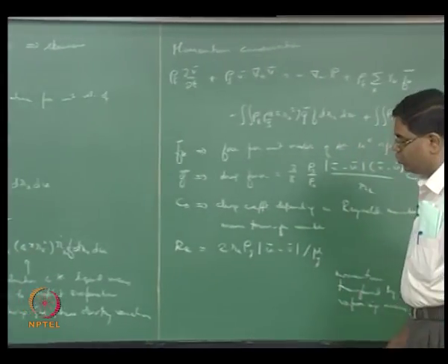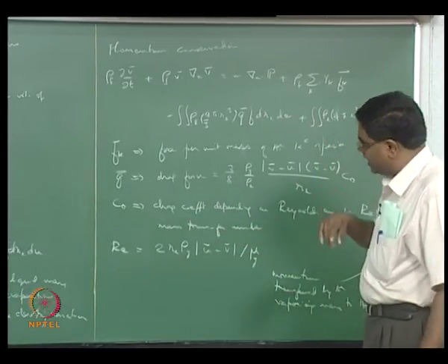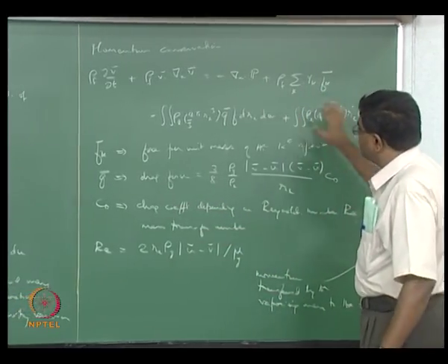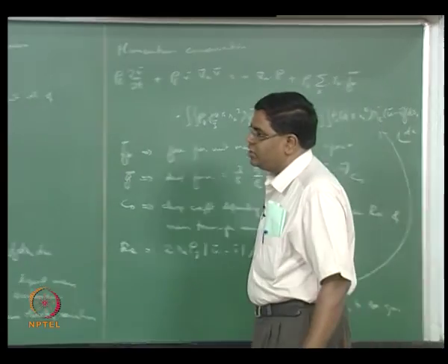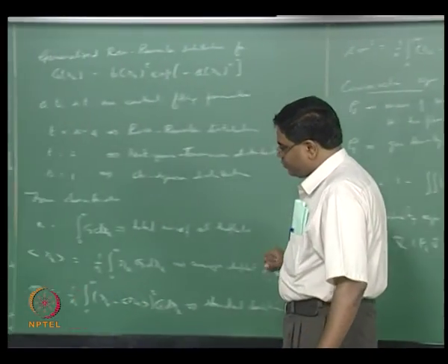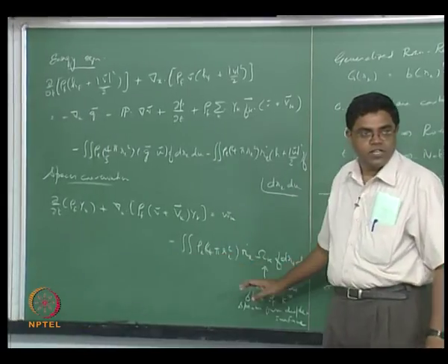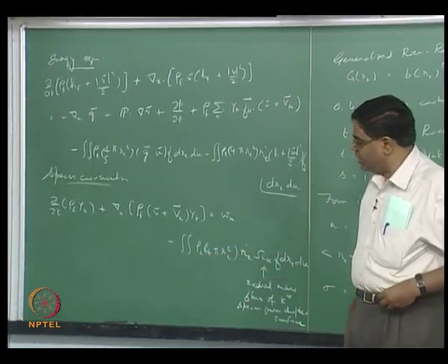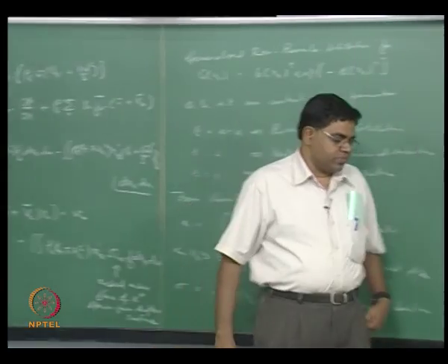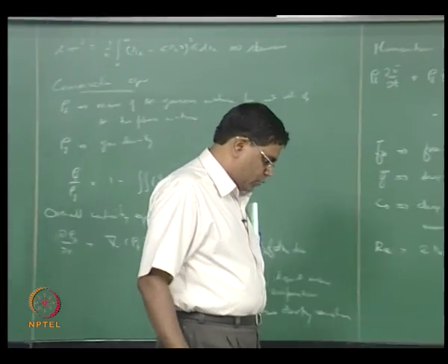That means the droplet would now add mass to the gases, it could impart momentum in a couple of different ways, energy in a couple of different ways, and also throw in a particular species into the gas, and therefore comes in as source terms in the equations.